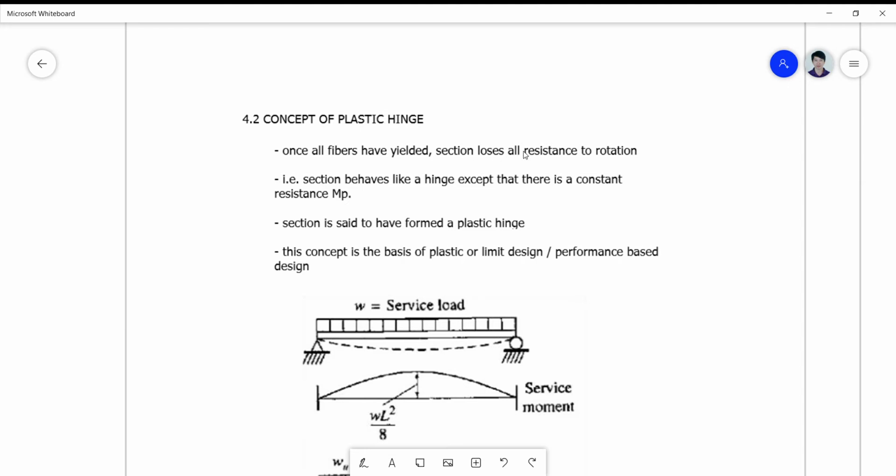Of course, I say some because normally in actual design, we do not expose 100% of such plastic rotation to occur. And this loss, maybe, is one way, shall I say, a disadvantage. Okay, so if you look at it one way, but on the other side, always look at the coin, no? Dalawa yung side niyan. When you say loss, parang disadvantage siya. Pero on the other side of it, there is some property that is being boosted, and that is ductility.